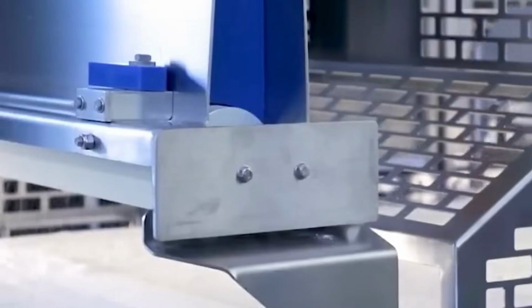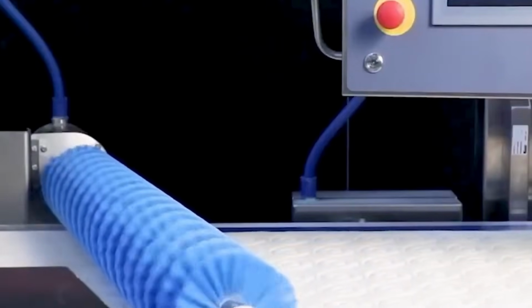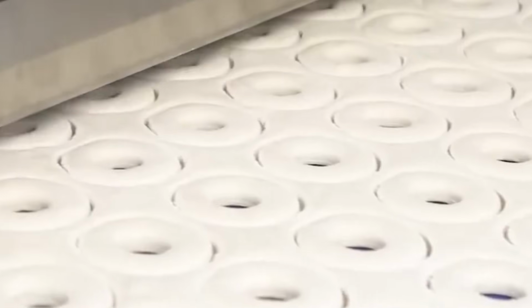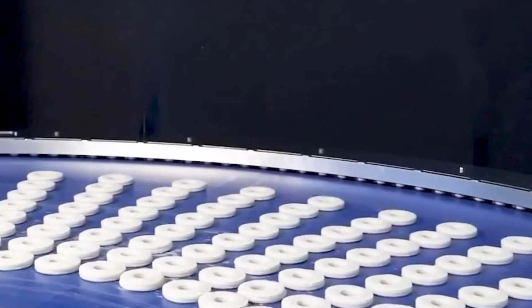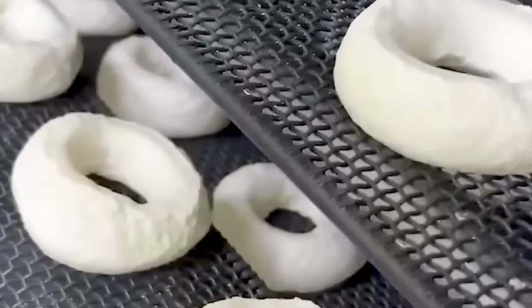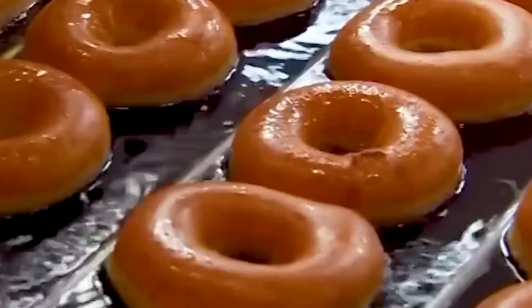For retail cases, sealed trays are grouped and shrink-wrapped using polyolefin film, which is cut, wrapped, and heat-shrunk in a tunnel oven operating at around 160 degrees Celsius. Each finished pack receives an inkjet-printed date code and batch number from a variable data printer. The printer adjusts to the motion of the conveyor, ensuring clear marking without interrupting product flow.